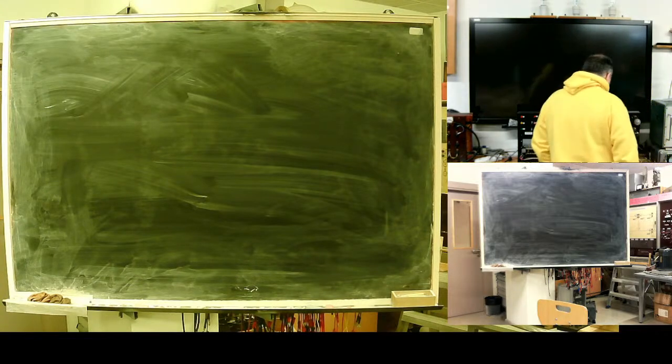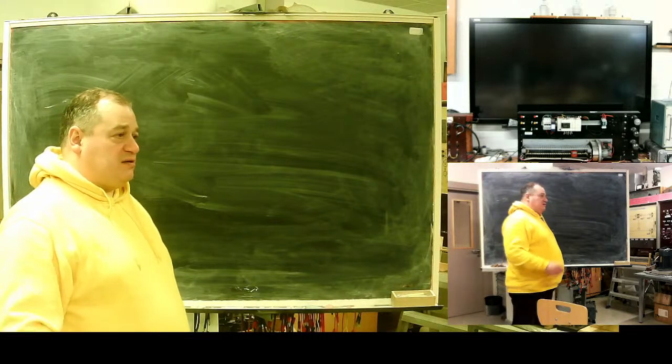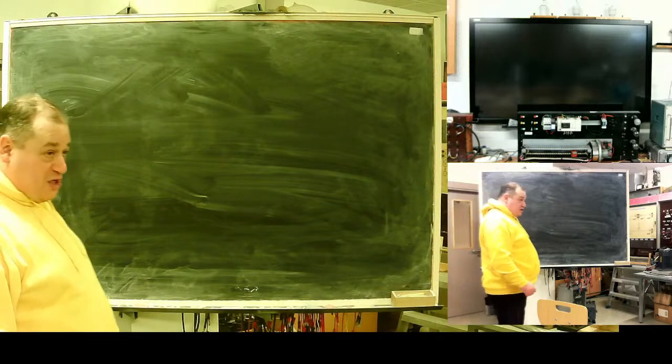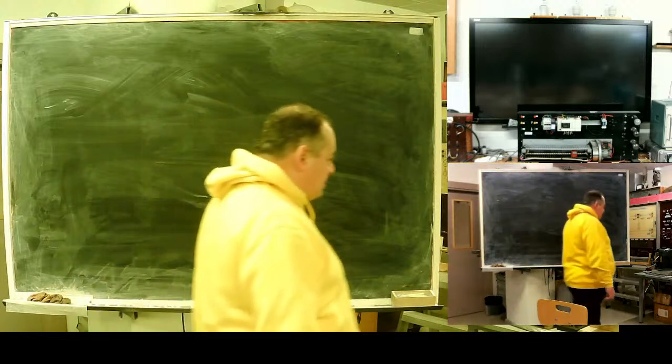faults occur. Different kinds of faults can occur. But statistics is a harsh thing, and statistics show that about 70% of faults are transient. They are not stable. A tree falling, all kinds of objects, insulation flashover. These kinds of faults are not persistent. It's not like a fallen tower, or I saw it in person, a large digger driven into a line. Transporters didn't bother to measure the height of the digger. That's a persistent fault, but most faults are transient, really about 70%.